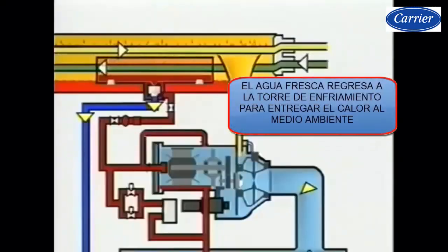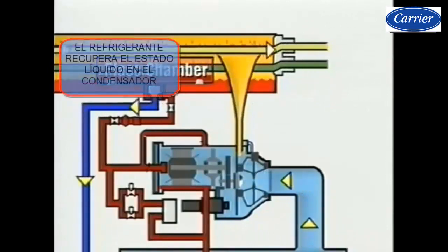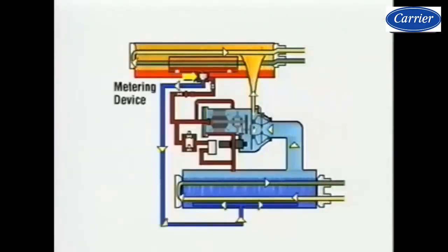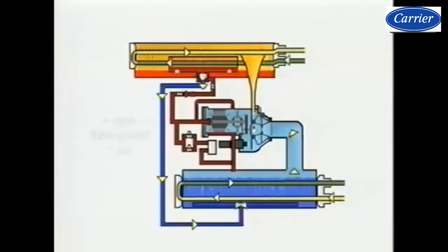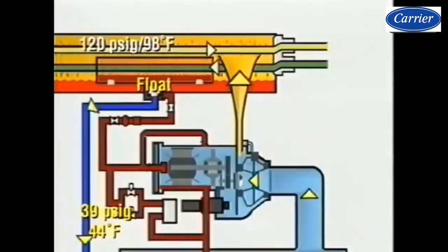It must be remembered that the advantage of water-cooled condensers is that they work at wet bulb temperature, which is very good for performance when we are going to install the chiller in places where humidity is lower. So these water-cooled condenser chillers have a very optimal performance. We have two factors that will greatly increase the performance of this unit: the centrifugal compressor, which in itself is a compressor with fairly high performance, and the evaporatively cooled condenser. If this chiller, which has this type of compressor, can be adapted to partial loads, we will have an installation with quite optimal performance.